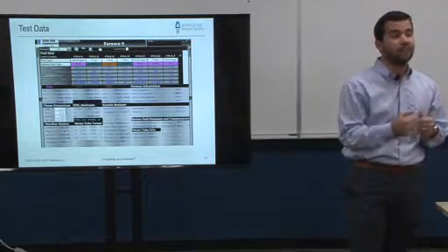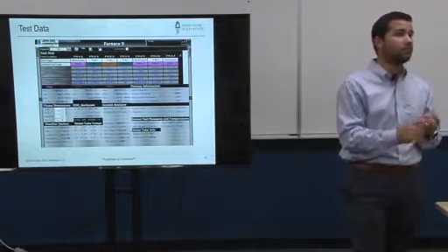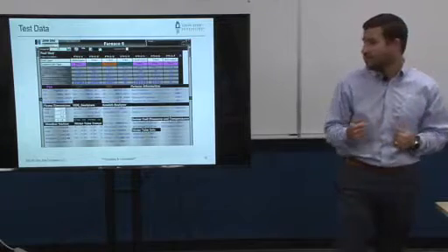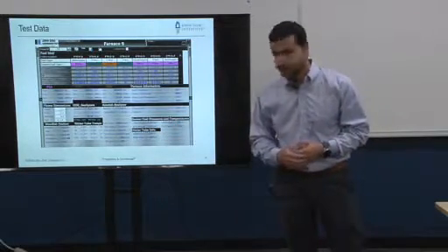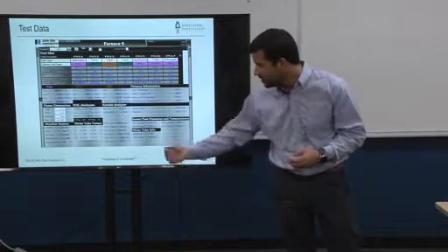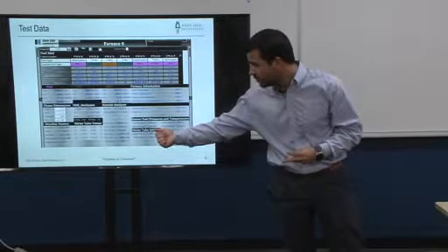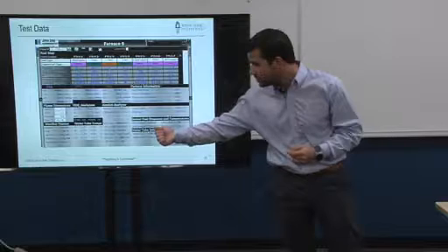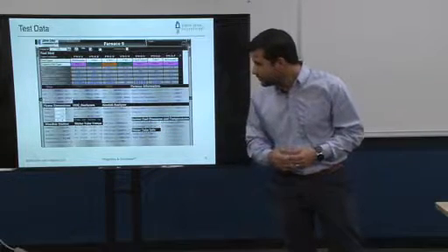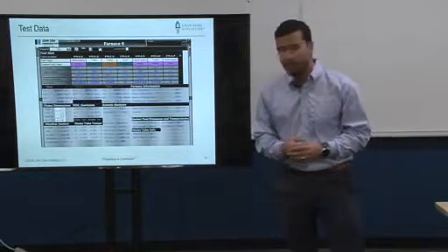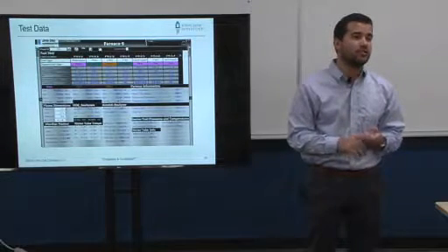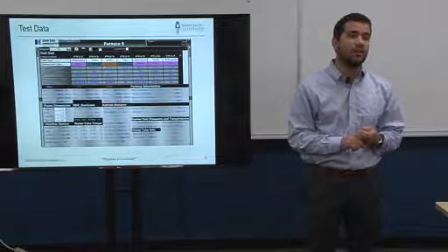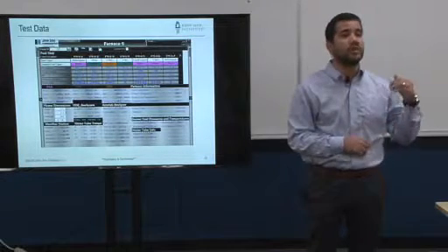Having the temperature and the fuel composition is really, really important, because off of that we get a pressure. In this particular case, that RFG pressure was operating at about 2.23 pounds, and the PSA pressure was 3.9 pounds. So knowing the temperature and your compositions is key in order to understand what the fuel pressure will be at the site.